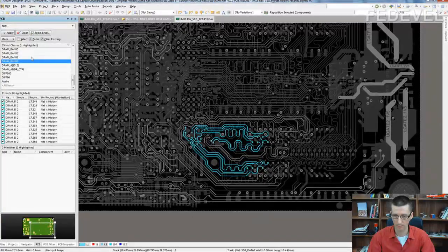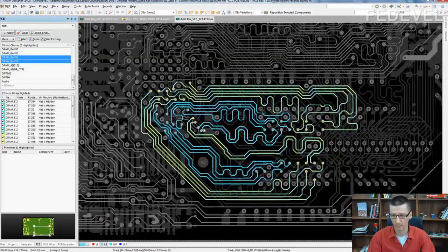I will show you. Try to route the differential pairs as neighbors, and do not mix the signals between the groups, because ideally you would like to also keep a bigger gap between the signals which are from different groups.